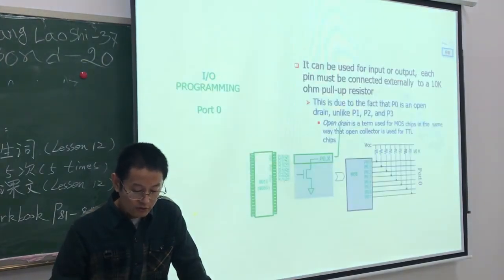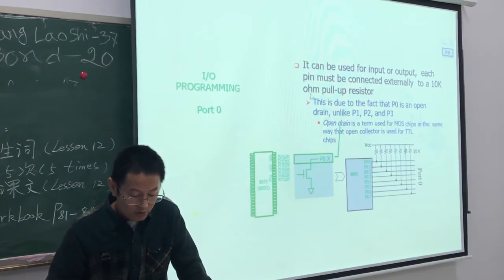It can be used for input or output. Each pin must be connected externally to a 10K ohm pull-up resistor.